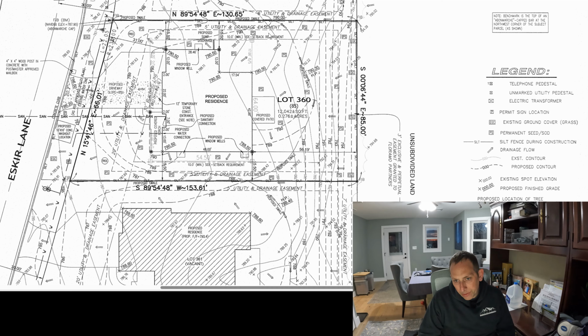These solid lines with numbers on them, and then you see these dashed lines with numbers on them. And you come over and go, what the heck are these? As you guys have seen very early on in our video when we looked at the GIS and we called up the topography, it showed all the topography lines. Well, you have those on your site plan as well, except these are going to be a little bit more accurate. Your solid lines are the existing elevations, the topography of the lot.